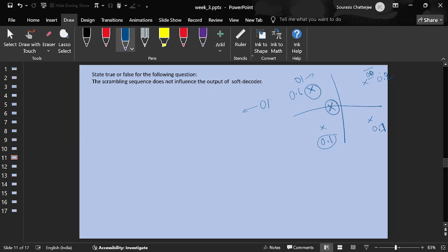To be honest, I don't exactly know the reason behind it, but as per my understanding, it has been verified experimentally that instead of doing hard decoding, if you do soft decoding, you are going to observe this 3 dB gain. Yes, this value is experimental, of course. But the reasoning behind it, I don't really know. But that's a good point, a good thing to look at if you want to dig deep into this.